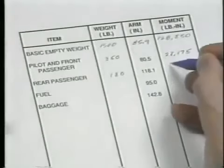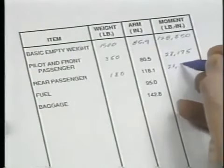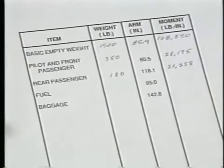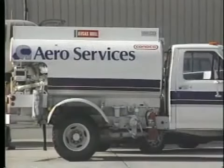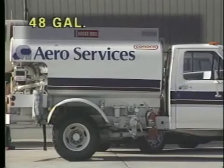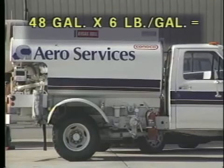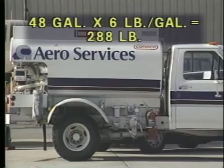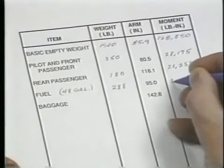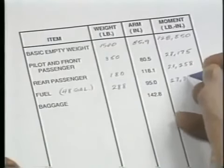The moment for the rear seat passenger is 21,258 pound-inches. The next major item is fuel. Since you intend to carry the maximum amount of usable fuel, which is 48 gallons, and since each gallon of avgas weighs 6 pounds, the total fuel load weighs 288 pounds. This weight times the arm of 95 inches yields a moment of 27,360 pound-inches.